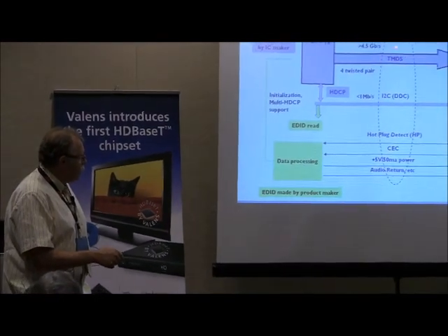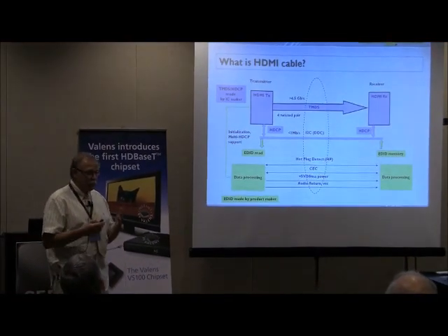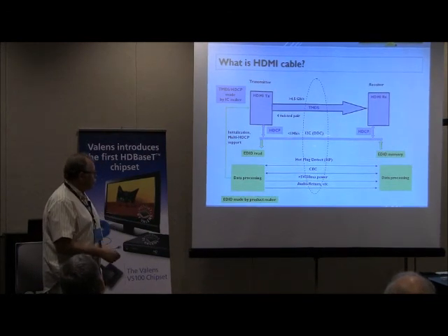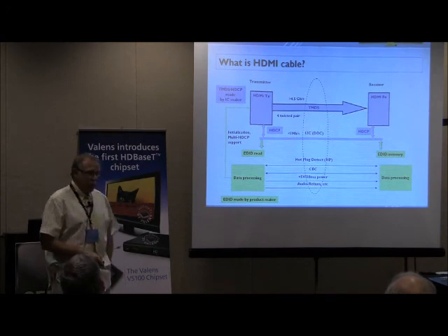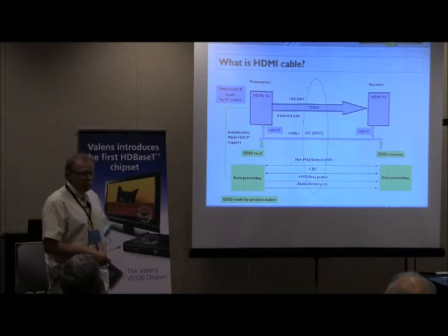Major bandwidth consumption is taken by so-called TMDS, that's the video and audio bus, that sends video from transmitter to receiver. There's also the I2C bus that allows interactive access of keys, encryption keys, as well as EDID information from receiver to transmitter.